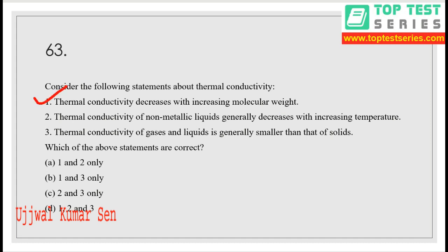We have to consider whether each option is correct or wrong, because they are asking for correct statements only. Option 1: thermal conductivity decreases with increasing molecular weight. Of course, thermal conductivity will decrease if we increase the molecular weight. Next, thermal conductivity of non-metallic liquids generally decreases with increasing temperature. It is also true, but only if it is a non-metallic liquid. For a metallic liquid, it will increase, not decrease.